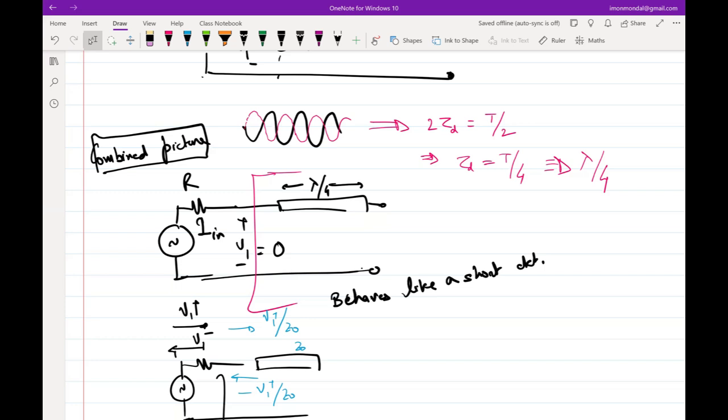Another application that you can directly think of: let's say you have a blocker at a frequency, and you design your transmission line in such a way that for that particular frequency of the blocker, it looks like a short circuit at the input. So the blocker will get notched out. If you tap your signal from here, and the signal is at a different frequency, the signal will not get notched out because for the signal the wavelength is different, but the blocker gets notched out. It's one direct application of how you can use it in RF to filter out blockers of a known frequency.